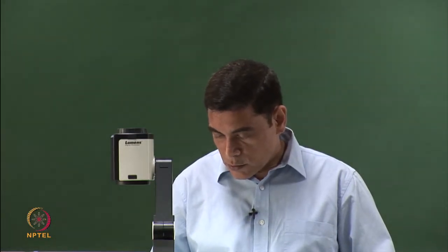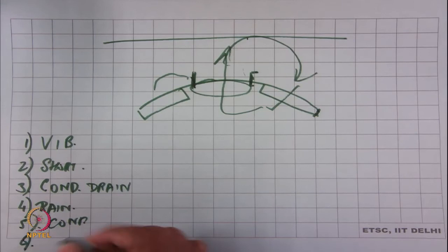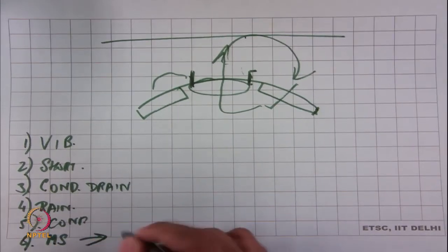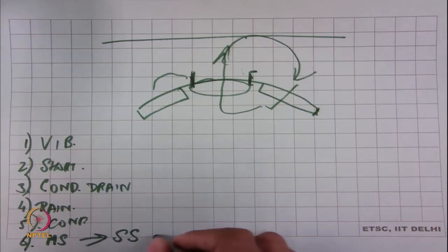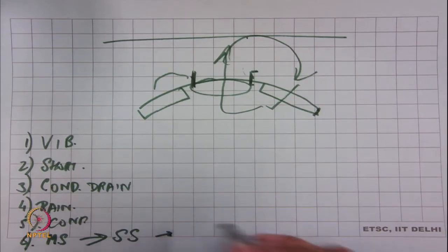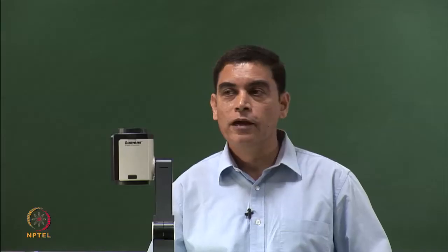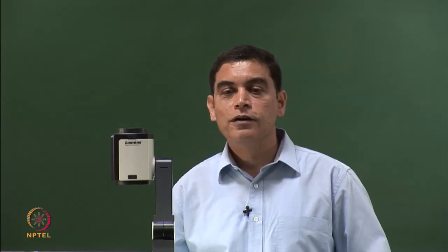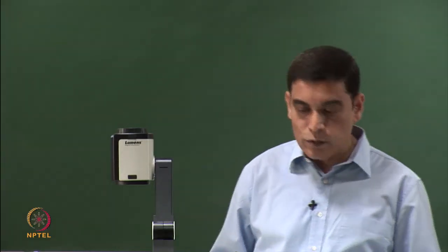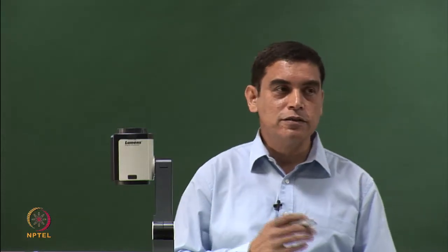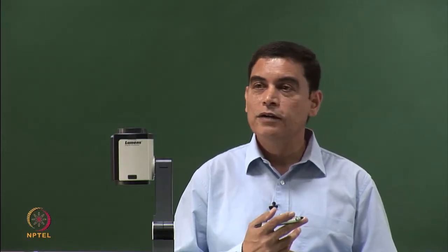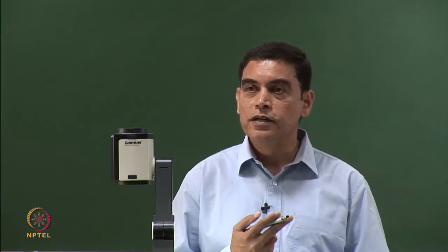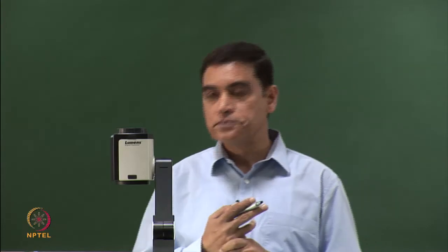So I talked about condenser motors. Then there was corrosion. The frame used to be made of MS. So from mild steel to stainless steel, along with the definition of a grade 304, was another change that happened. And for RDSO, it is simply one spec change. They don't want to paint it, they want SS. But at the manufacturing level, you certainly need to be prepared to weld thin sections to thick sections. You have a frame, and the entire welding apparatus needs to change, the skill level of people needs to change. So all that was another learning.